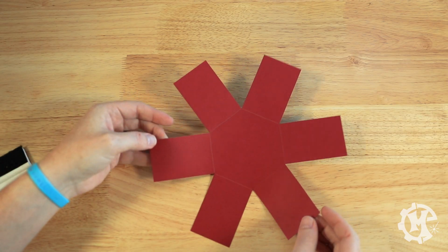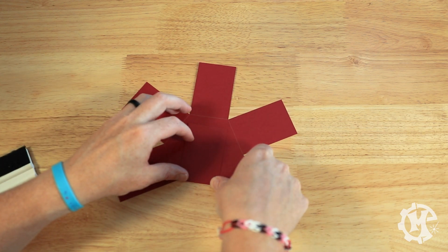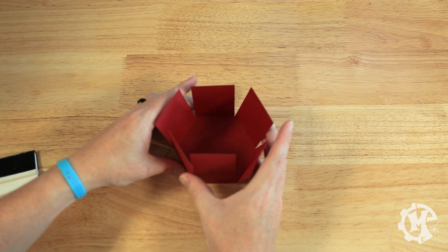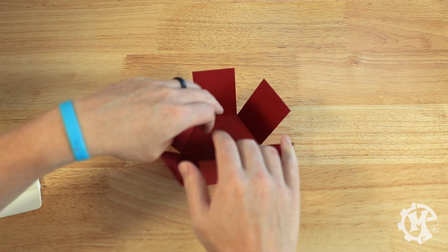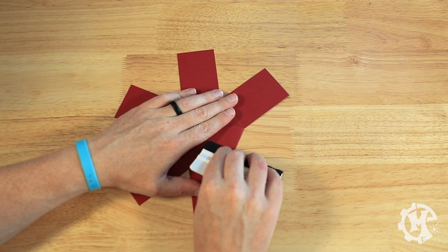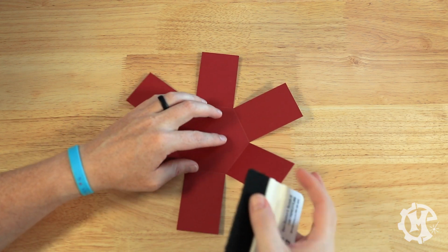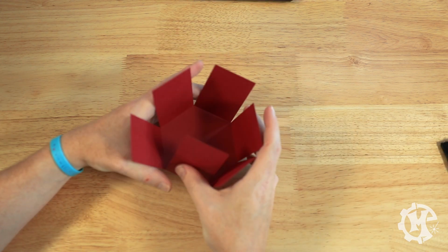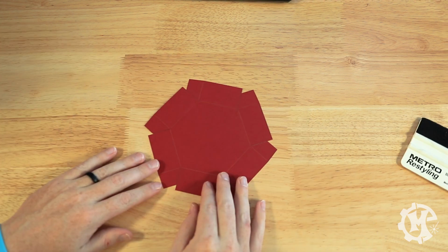This is how this piece comes off the laser. You can see the score lines. So just go ahead and fold onto those. The tricky part with this is even if you fold them all up like the box is going to be and you let it go, you can see they don't necessarily go down right away. What I like to do is take one of my vinyl wrap squeegees and just kind of press it on that fold line to make it a little bit better. And what we'll do is we'll go back and forth a little bit here in a second. Once you think you've got it enough, go ahead and give it a test, let it go, and that's what it should do.